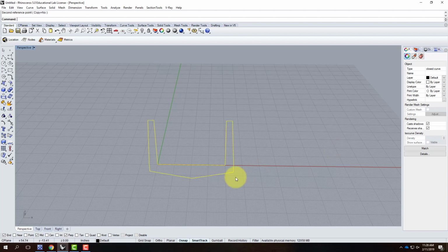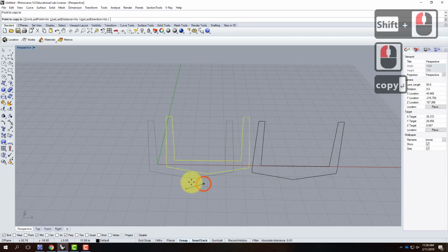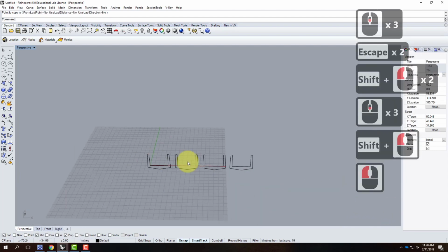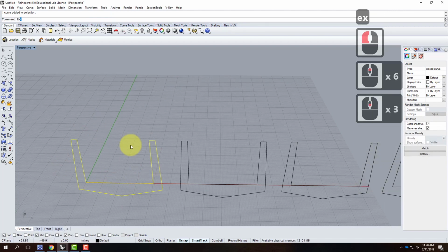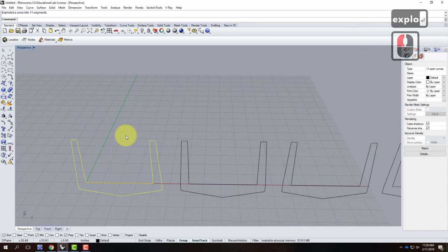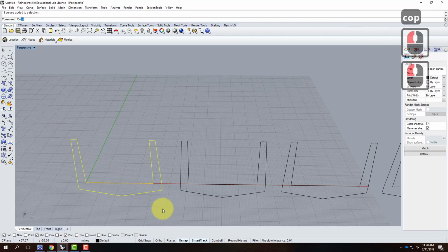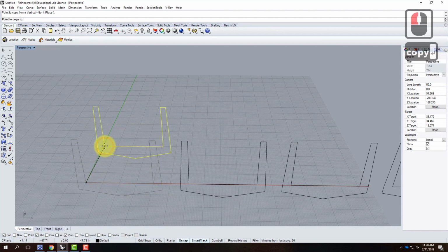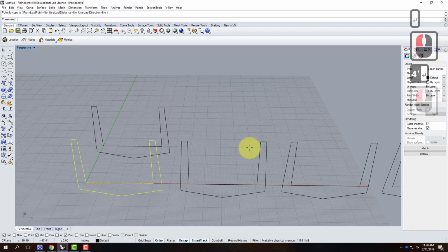I'm going to go ahead and copy this so that I have a couple versions of it so that you guys can see me do it a couple different times. And I'll show you some of the different strategies. The first strategy would be to take this, and I'm going to go ahead and explode it to simplify it. And then I will take this whole shape, and I'm going to copy it. So I've typed copy again. And I'm going to go back by 4 feet. So I'll turn on ortho and type in 4 feet, and that gives me the second copy.